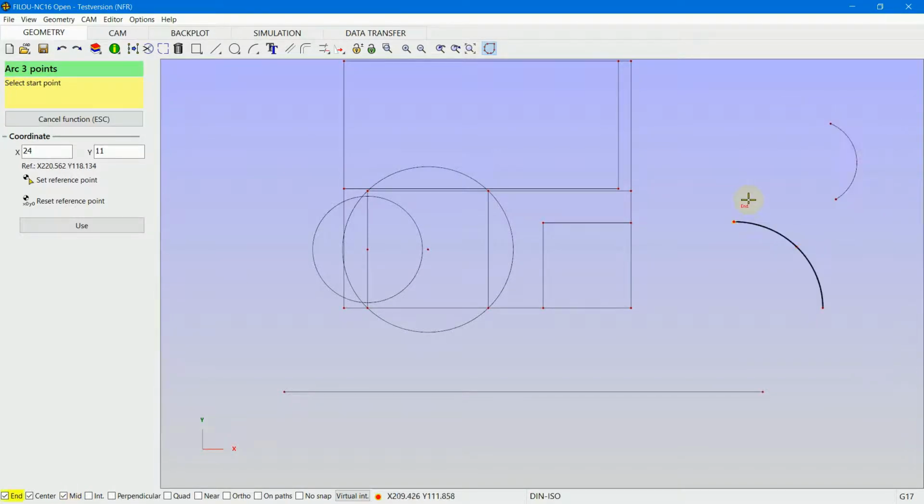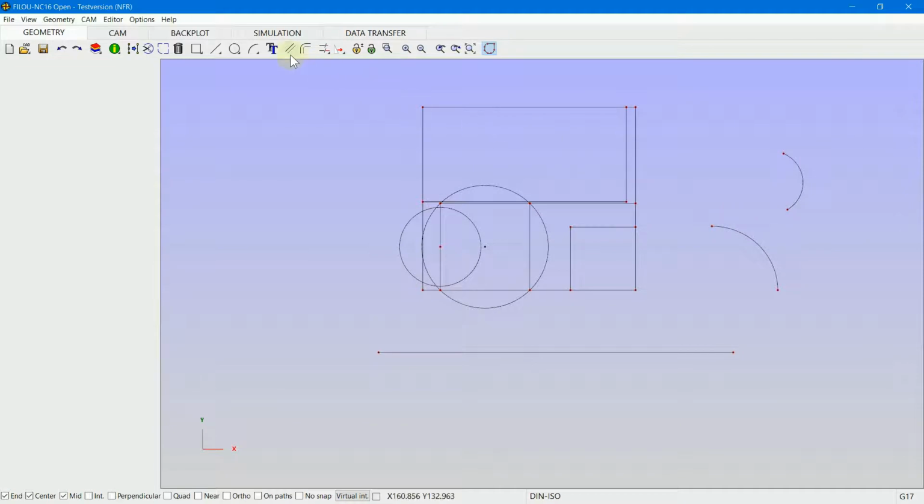Interesting is also the parallel element. It is an offset from a given geometry. When we select this tool, I can set the offset, let's say 3. And when I move to an element, like to this arc, it depends on which side of the arc the mouse is. When I have a preview like this, and then when I click, then we have the offset element ready, and to this side is another possibility.